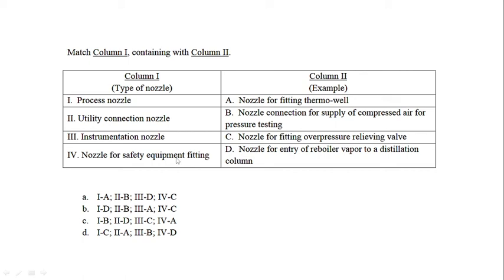And the common range will be, it can read from minus 200 degrees Celsius to 850 degrees Celsius. But it is more expensive than a thermocouple because platinum wire is used, and it gives a linear response because temperature varies linearly with resistance. So here both the statements are true, so the correct answer will be option B.